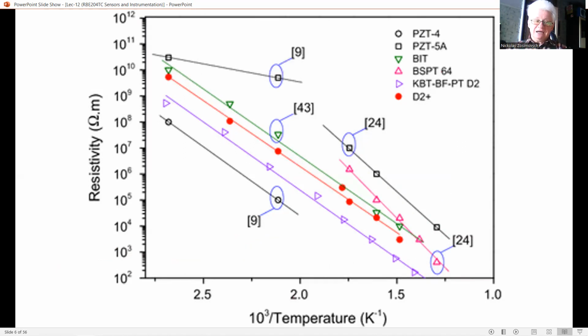Secondly, a temperature change may induce crystal deformation and hence an electrical output as well. Further, materials connected to the piezoelectric crystal, for instance clamping parts and electrodes, may have different thermal expansion coefficients. In this case, the crystal experiences unwanted forces.